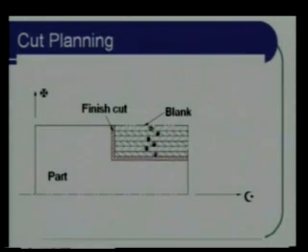For example, let us see here, this is the part that I have, and we want to make a rough cut. Now this is the maximum depth of cut that I can take with the tool. So I will be taking a number of rough cuts, this 1, 2, 3, 4, 5, 6 rough cuts, in order to remove the bulk of the material, and with the leftover material I will take a finish cut, so that I will get the smooth surface that is required.